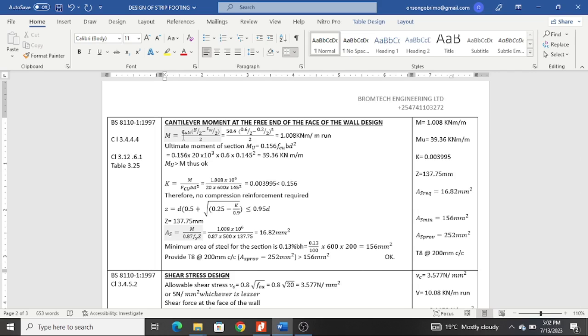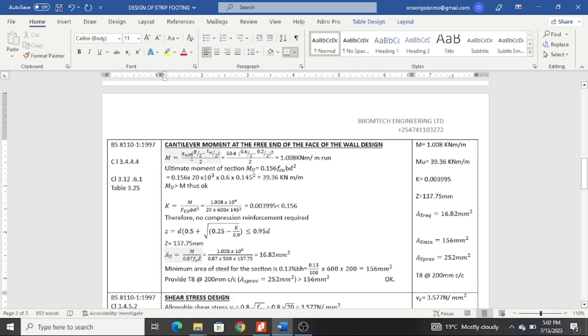So you do the Q ultimate, multiply into B, this is the width, subtract the thickness of your wall, and then this is divided by 2 and this is divided by 2. And of course you need to square this and multiply it by Q ult and then divide by 2. And I think here there is a mistake because this is not squared. Let's correct that right away.